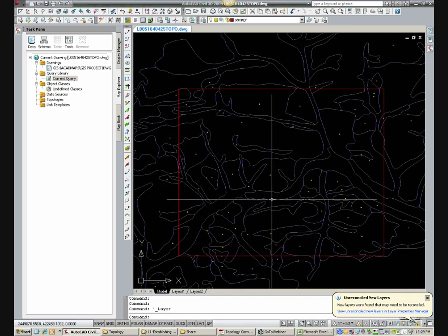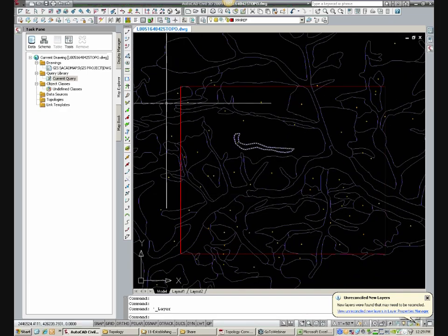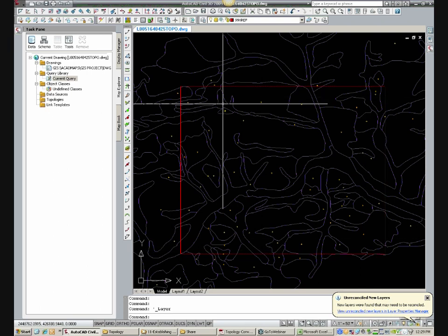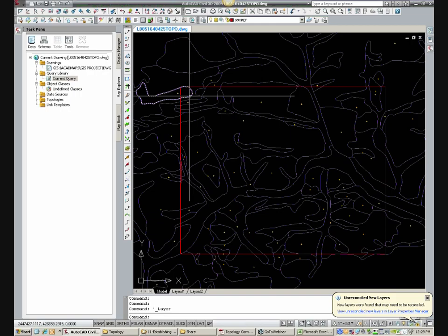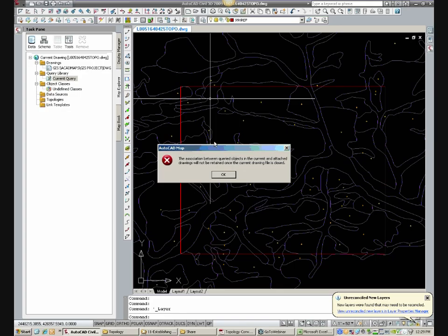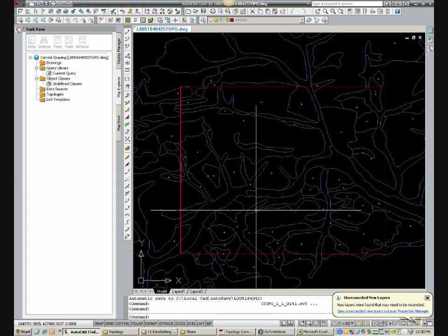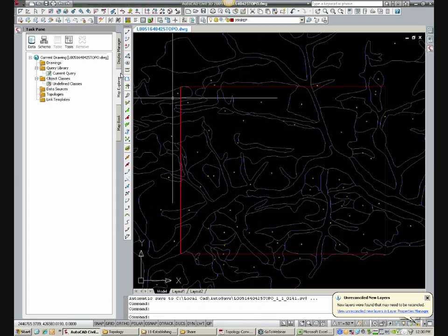Then the next thing I'm going to do is bring these soils into my little area here. So I need to refine these soils, and this is a very difficult part of this procedure. This is where people get bound up. That little message says I need to detach my map from the W drive. I figured out a workflow to do this as easily as possible, and let me show you what the next step would be.